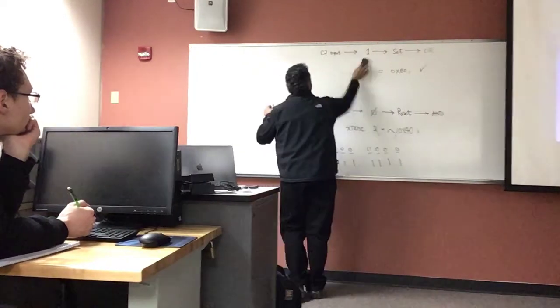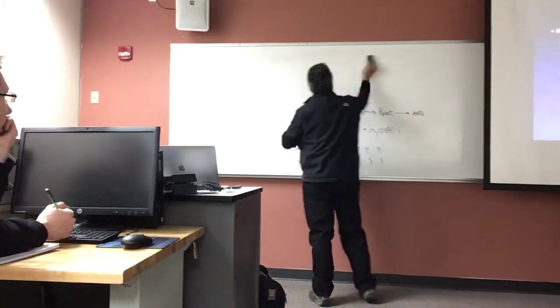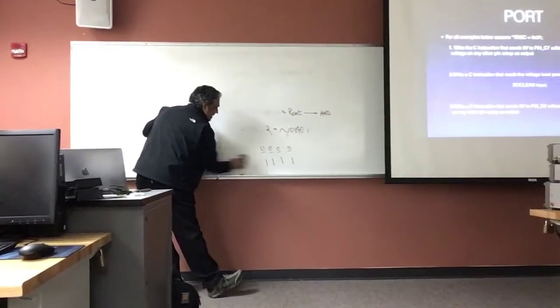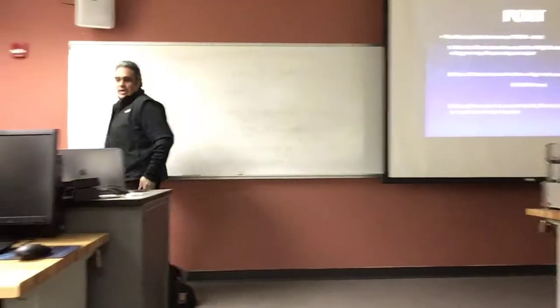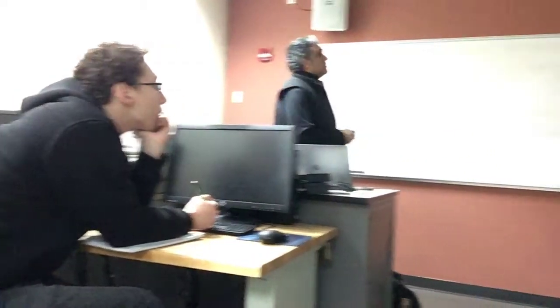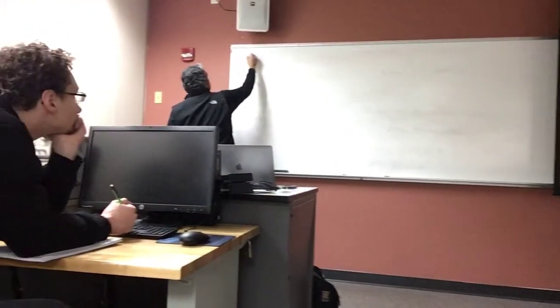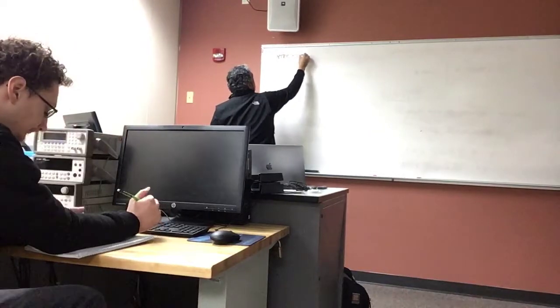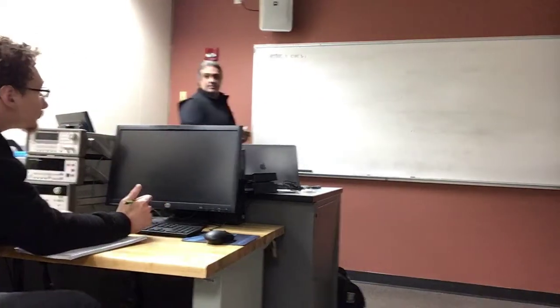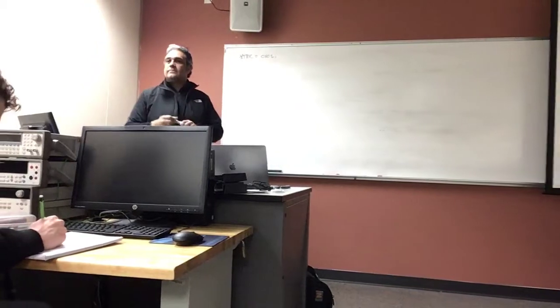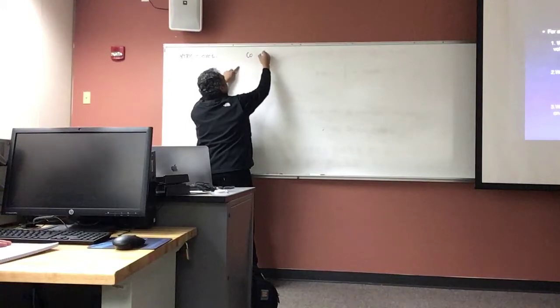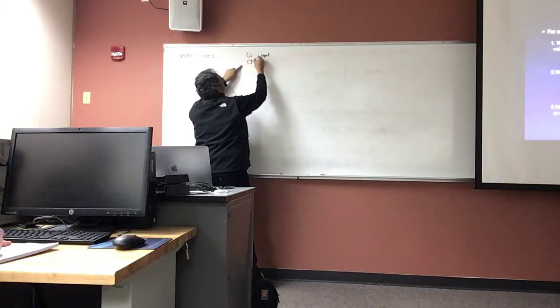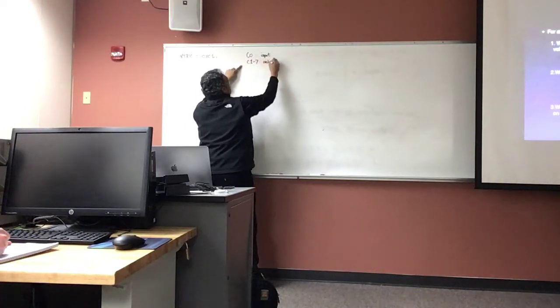The reason why that is important is because once I give you a tri-state value, input versus output, whoever is an input and whoever is an output is already set. Right? So, I'm going tri-state C equals hex 1. What does that mean? The least significant bit, C0, is an input, and 1 through 7, these guys are outputs. That's what that means. Right?